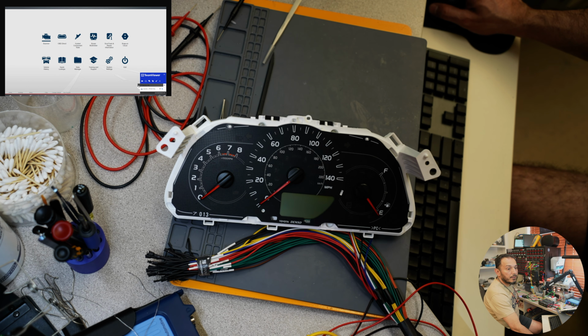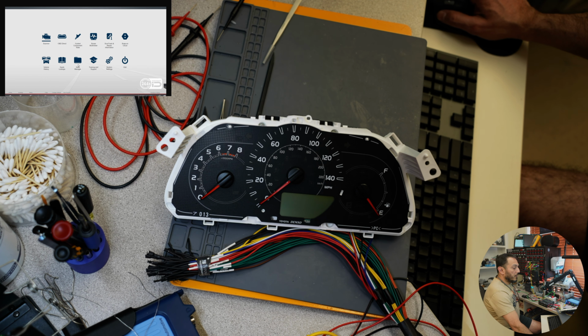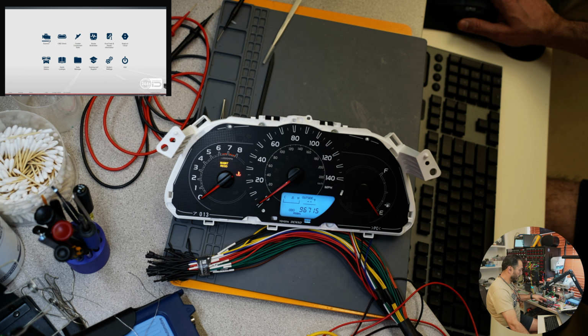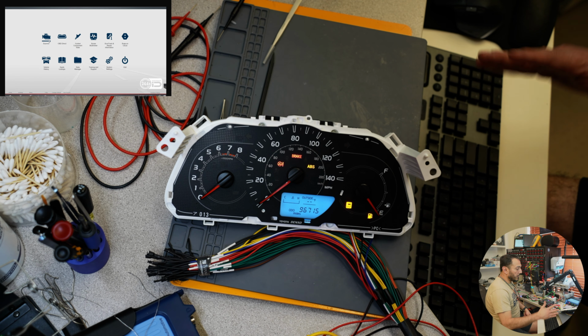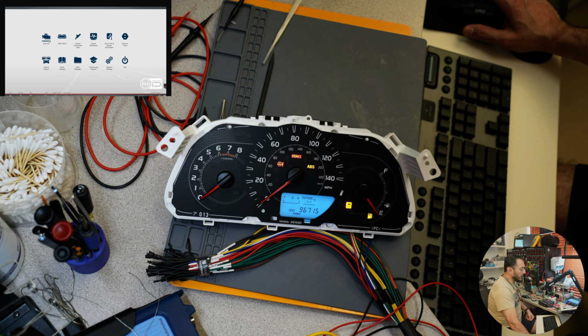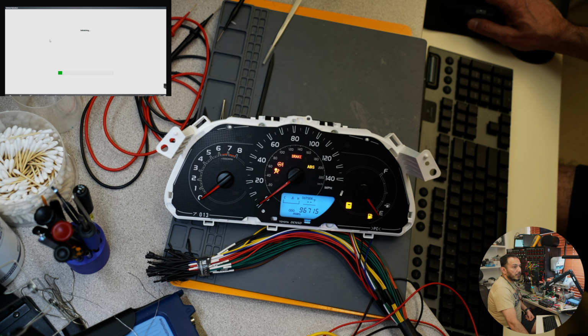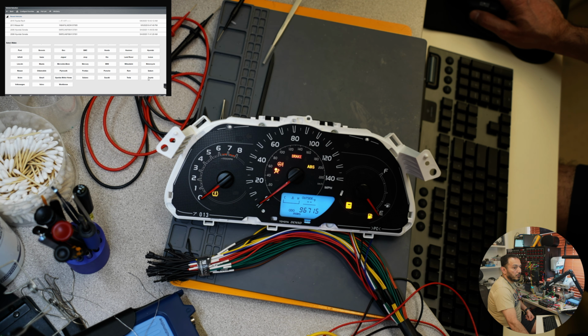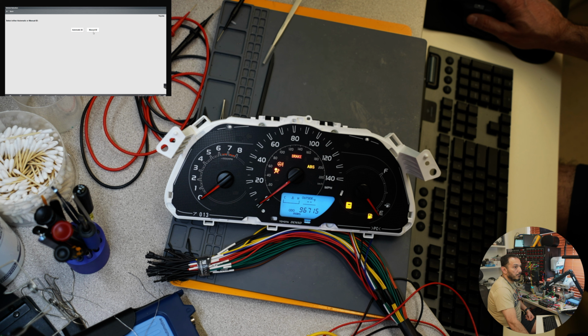All right, we got the scanner on there, which is good. Let's power this up. So everything is ready. You saw the needles shaking and moving in there, but that's the normal procedure, and we can see 96,715 miles. Now let's go over to the scanner. We're not going to do an automatic ID because it's just the instrument cluster, so we're going to manually select the vehicle.